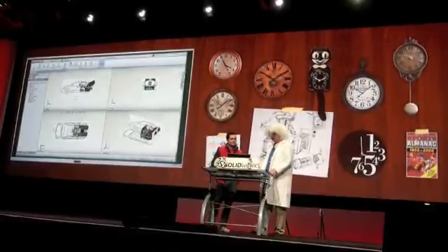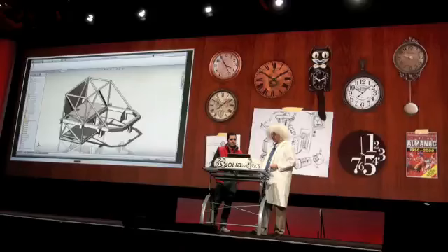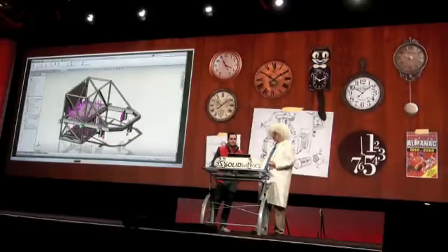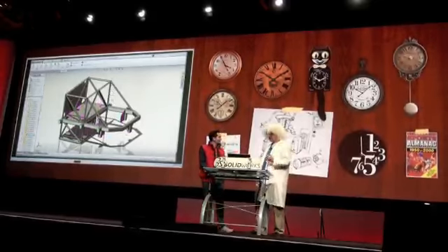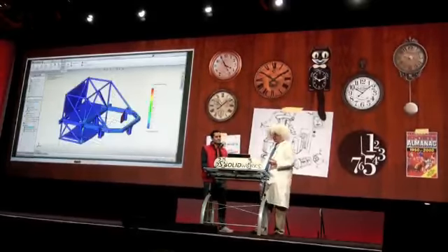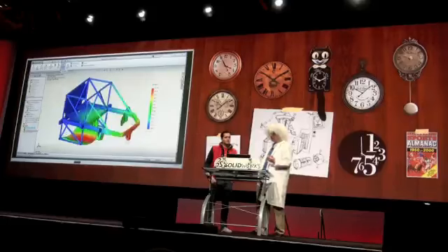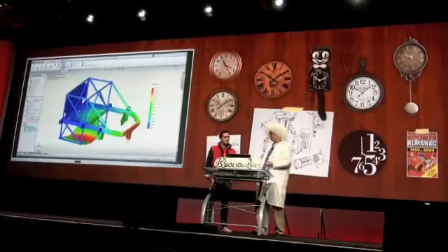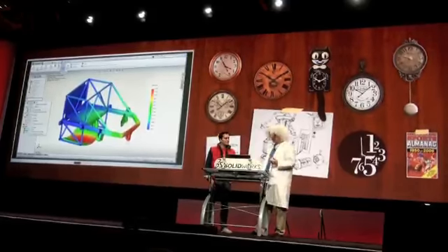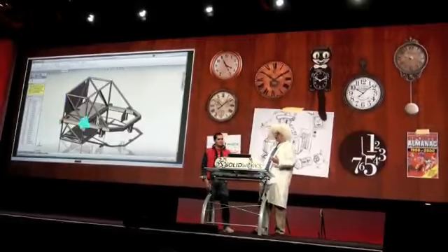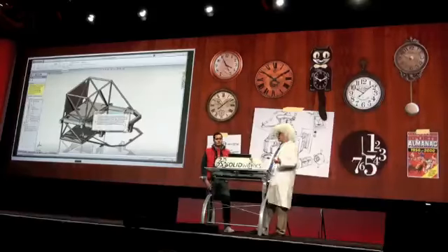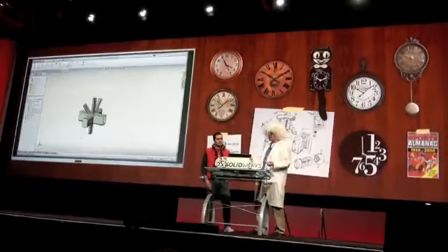Absolutely. And get a load of this. When I was looking at the frame for the retrofit, I came across a new sub-modeling simulation capability in 2013 as well. It automatically takes the loads and boundary conditions of the study, and applies those to some subset of the design for a more in-depth analysis. So for massive structures with complex loads, it's really easy to zero in on the local areas to evaluate aspects like welds or bolted connections.